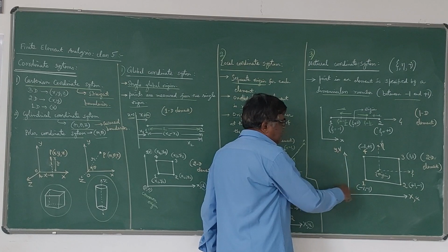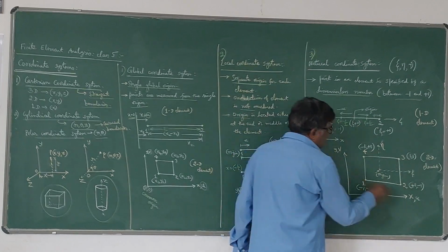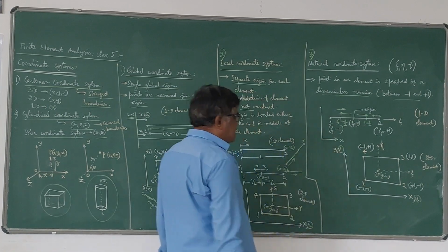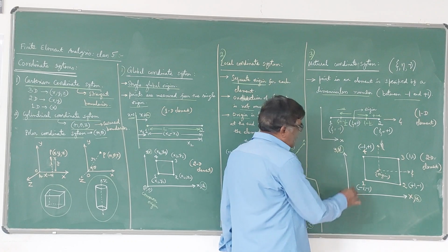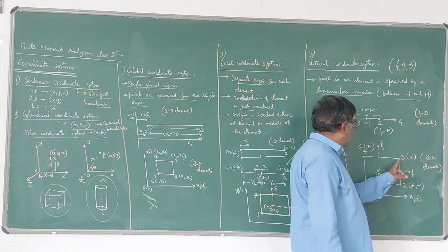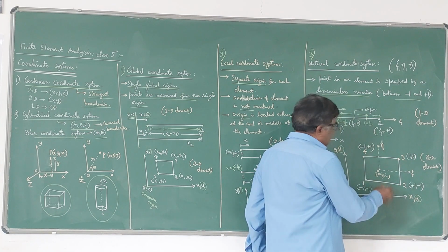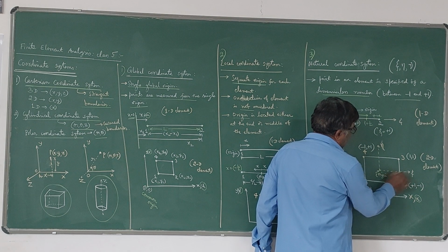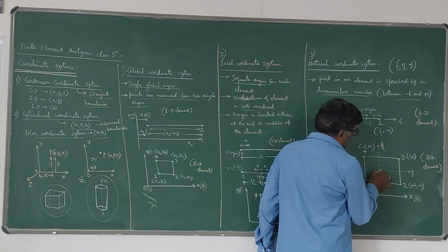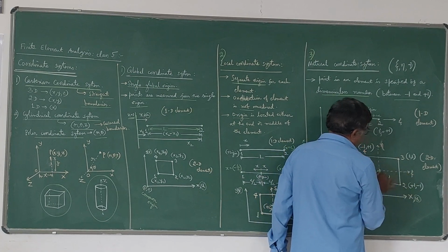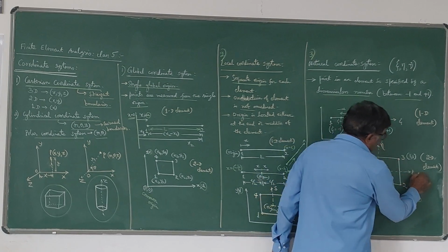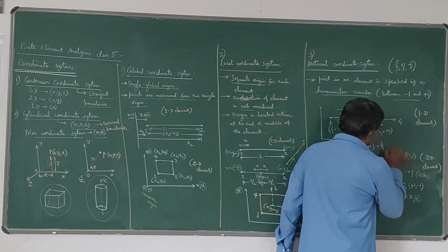Suppose the same thing for a two-dimensional element. As you know, you have two displacements u and v along the x and y directions. Similar to this, if you take a quadrilateral element, 1, 2, 3, 4 are the nodal points, and here the origin is taken. Please note that the origin is the center of this quadrilateral element. Parallel to the x-axis, you draw the zeta axis, and parallel to the y-axis, you have the eta axis. So zeta, eta. This is the zeta pronunciation. This is eta.